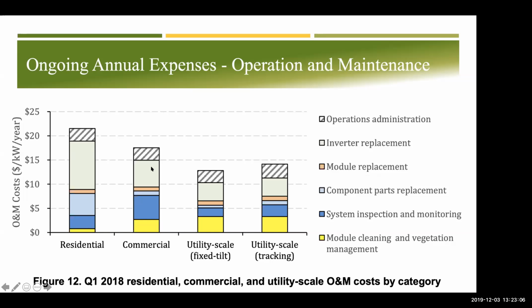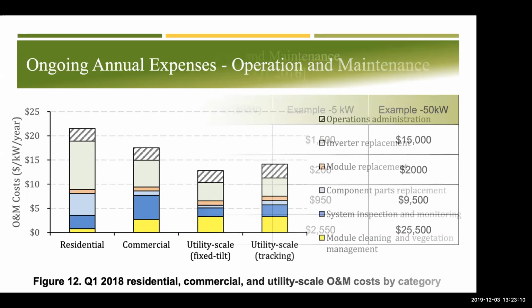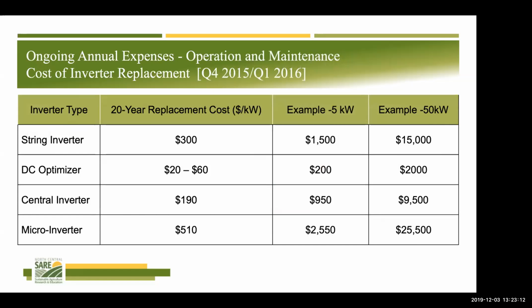And that tends to be the item that is most prone to failure. As you think about inverters and operations and maintenance, it is something that, just through regular O&M, you can increase the life of the inverter by making sure things are properly torqued and connections have the proper torque levels.